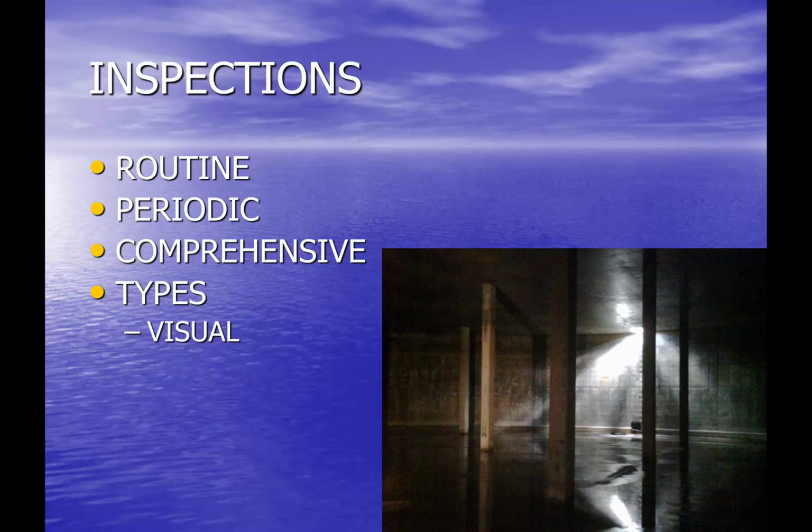The first is what we'll call a visual inspection. This is simply draining the reservoir, maybe 50%, and looking through the hatch and seeing what we can see. And this is typically something you might do between the more detailed, comprehensive inspections, so we don't forget about it in between and just look and see, all right, from the surface, is there anything I can see?